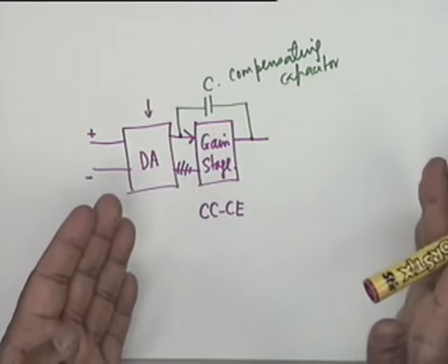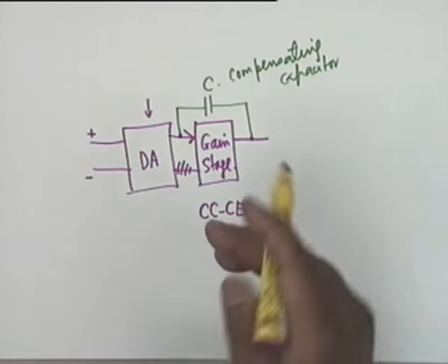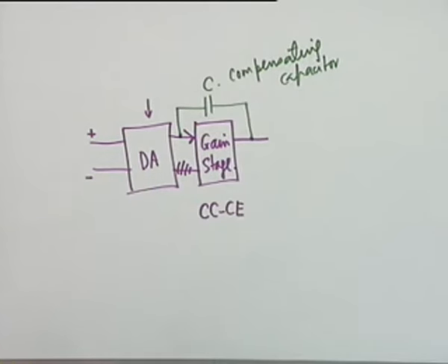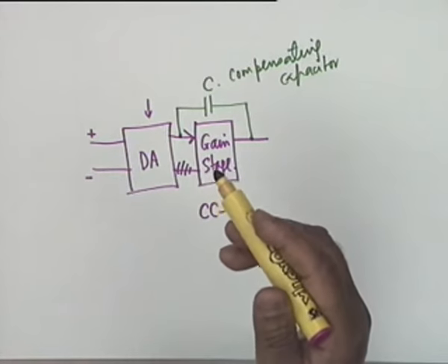Because differential amplifier gain stages we can design for several megahertz cutoff, but usually a capacitor is attached from the input to output to bring down the 3 dB point to several tenths of hertz. How does it do it?